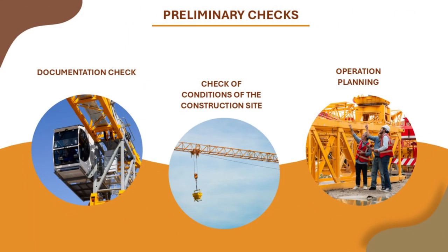Preliminary checks. Documentation check. Verify that the crane has the CE marking and instruction manual and complies with current regulations. Ensure that the periodic checks required by law have been carried out and that the relevant maintenance log is present.